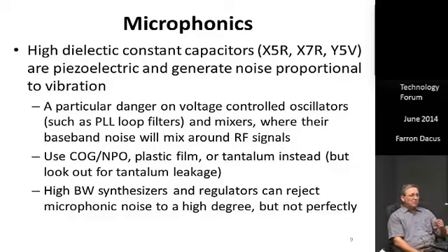I'll talk a little bit about some noise issues later, but the reason noise is so important in RF basically comes down to dynamic range. You take a 1 watt transmitter and you try and get some range out of it down to, say, a receiver sensitivity level, which for low data rates might be minus 120 dBm. That is a 150 dB dynamic range.